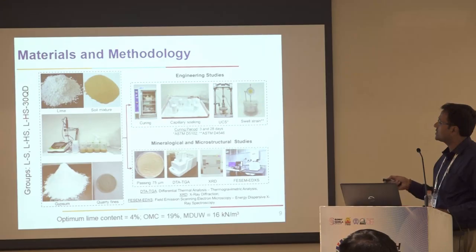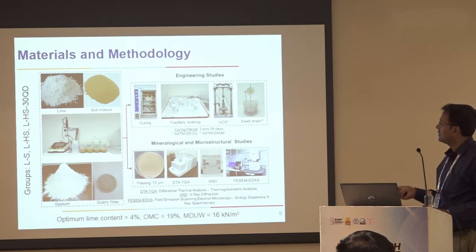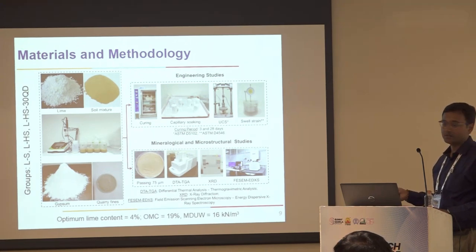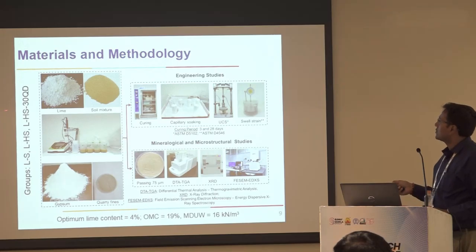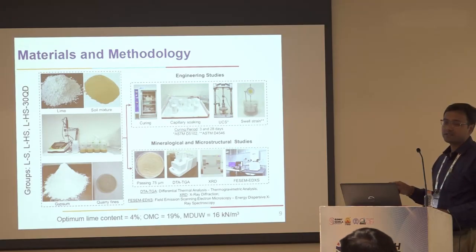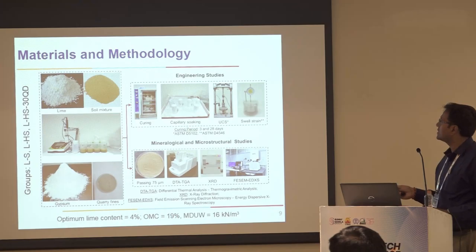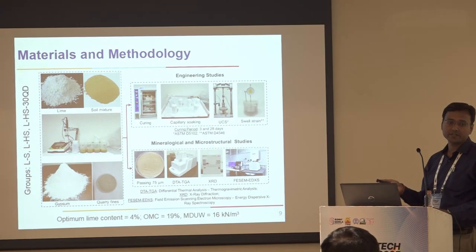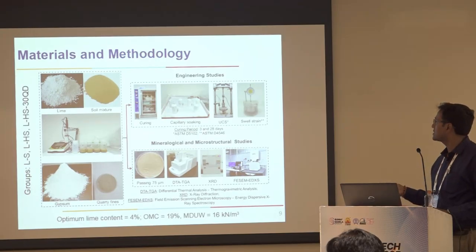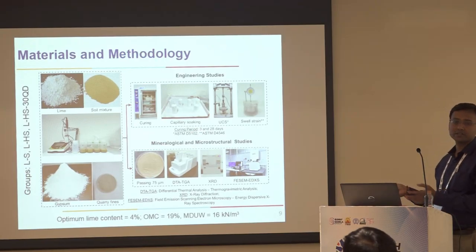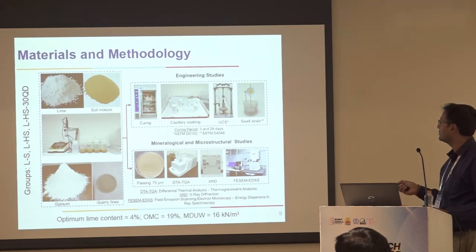And the last group we are considering is the LHS-30QD, which is this soil mixture with the sulfate content increased using gypsum. On top of that, we are using quarry dust fines as the co-additive. For these three groups, we prepared cylindrical specimens for strength testing as well as swell testing. The samples were cured in a temperature-controlled humidity chamber, and here I am showing the data for only two curing periods, 3 days and 28 days.